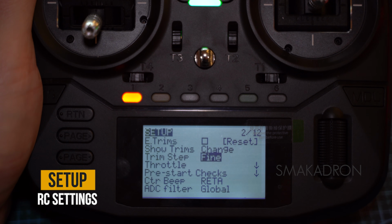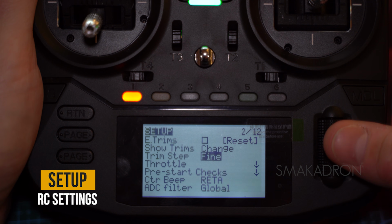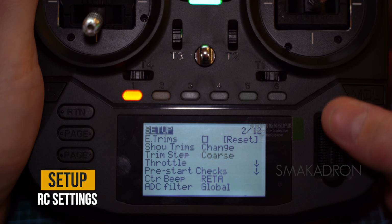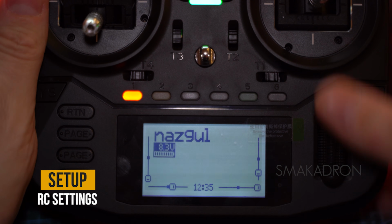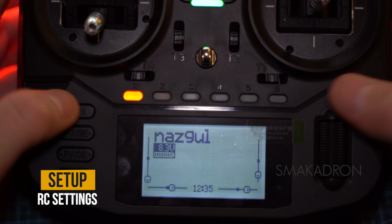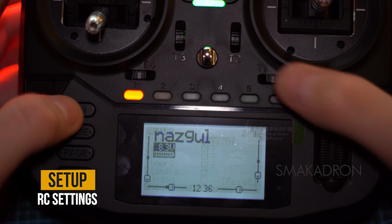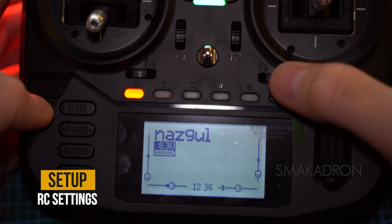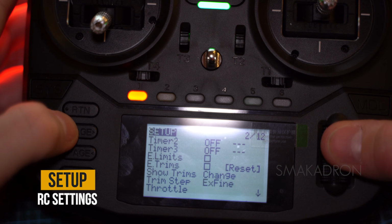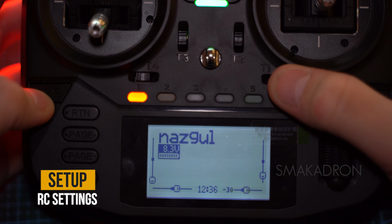Trim step defines the size of the adjustment step for the trims. This determines how large or small the changes will be with each press of the trim switch. The trim step size can be configured to your needs. Coarse, a step of 1.6%. Medium, a step of 0.8%. Fine, a step of 0.4%. Extra fine, a step of 0.2%, the smallest step. Very precise adjustment.